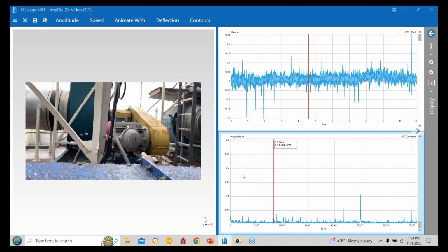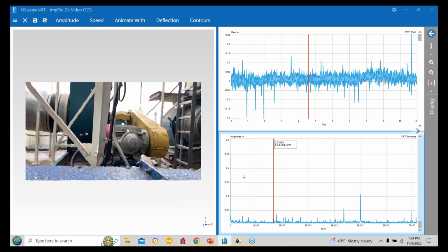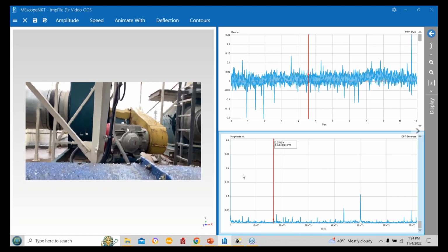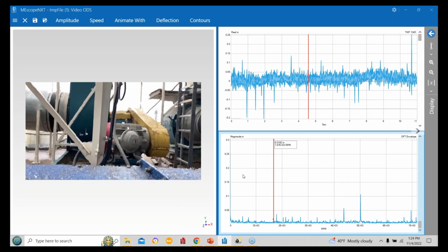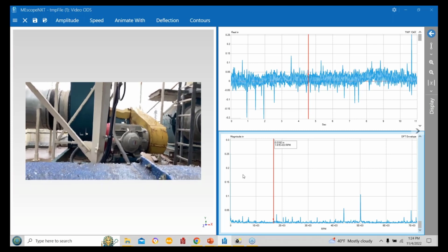And some of them are aliasing peaks. If you don't sample fast enough, you can't get enough distance away from the high frequency peaks, and they tend to roll back into the low frequency end of the spectrum. They fold over. I will show you an example of that graphically, which makes a lot more sense, in a few minutes. I just want to go through the wizard first.